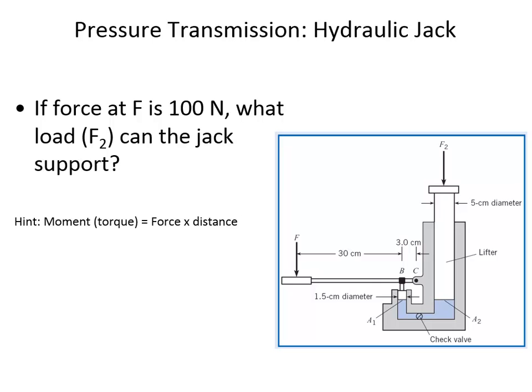These are at the same elevation. Now, what if they weren't? Like what if this plunger was down a little bit and this one was up a little bit? Yeah, the pressure at 2 would be a little bit lower, but compared to how big this pressure is, it really wouldn't matter. Even if it was a meter higher, the difference in pressure would be so small it's negligible.